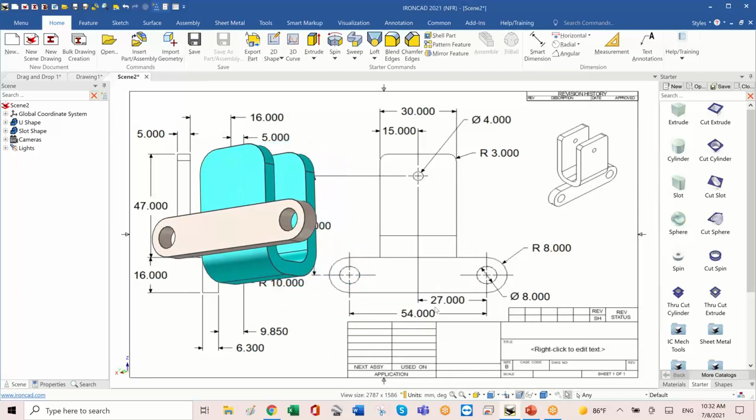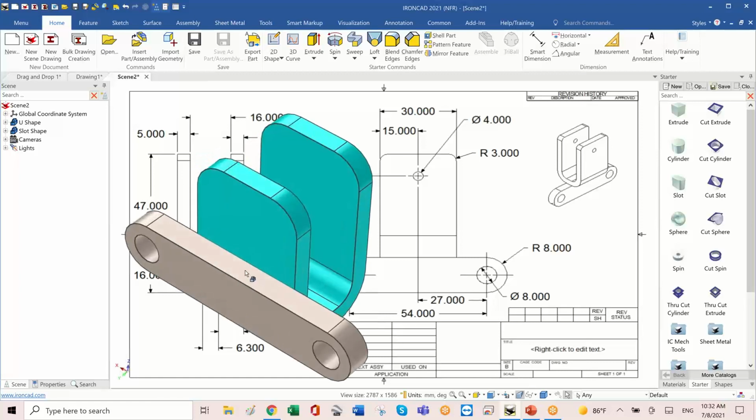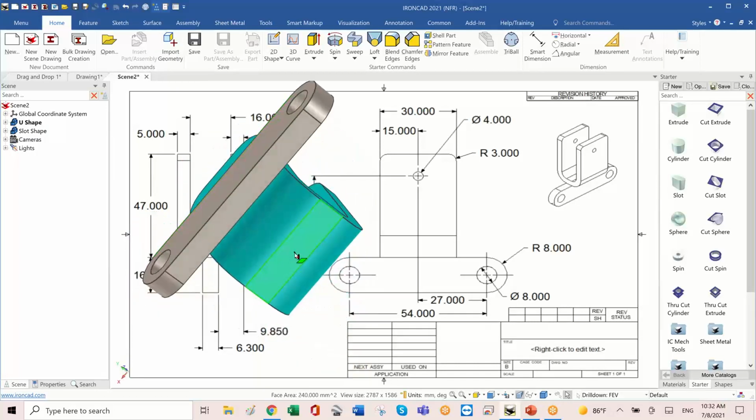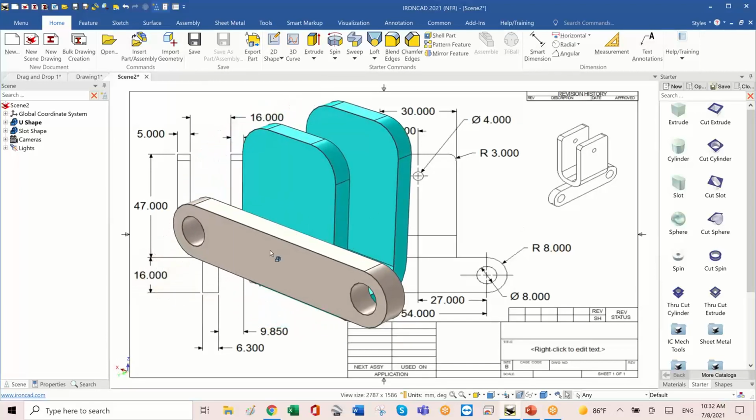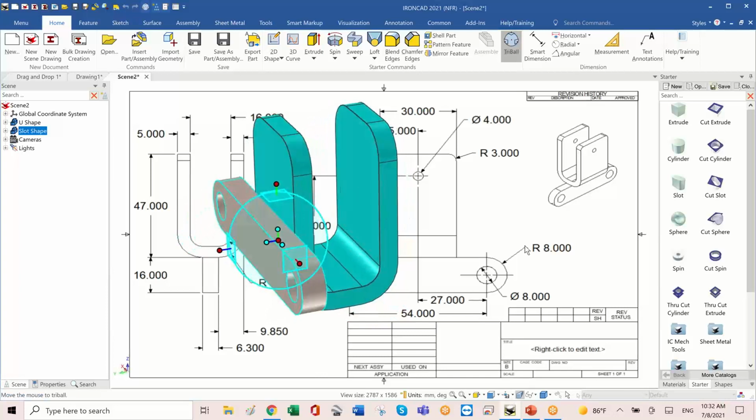What I see is that I need the top center of this shape right here. I need this point located right at the top of this point. And for that, I can introduce the triball, which really is a cool thing, and I'm going to show it to you now. The triball is how we move parts around.